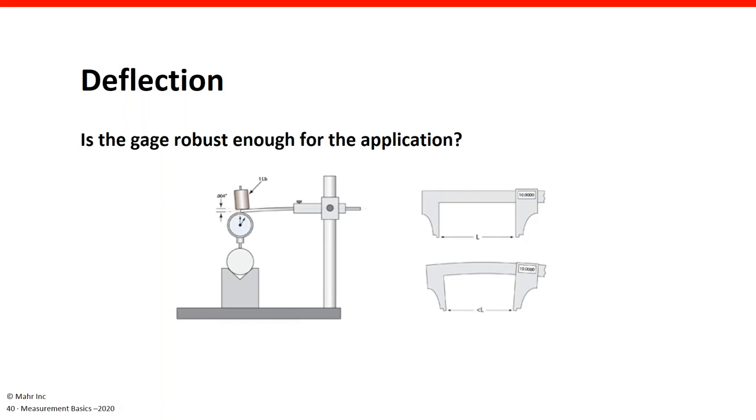And even with a caliper or micrometer, sometimes some of them, again, because they're influenced by the operator, not every operator has the same gauging force that is used with that instrument. So a person with a pretty strong thumb might be deflecting the instrument and causing a little offset in the readings. So deflection is built into everything, but you can control that by knowing the forces and building a good, stable gauging station.